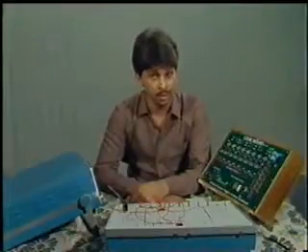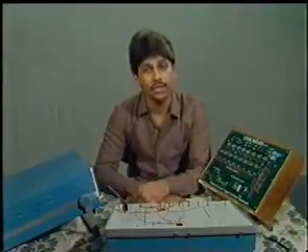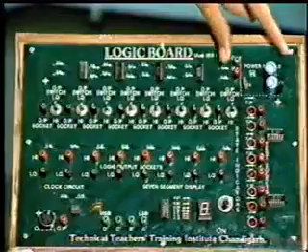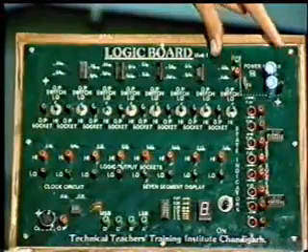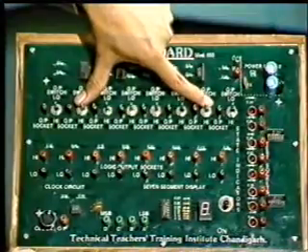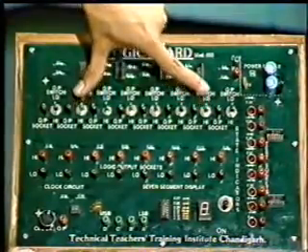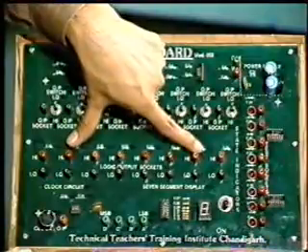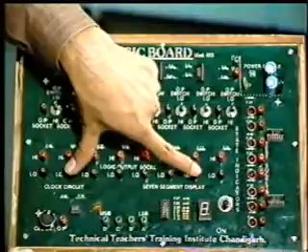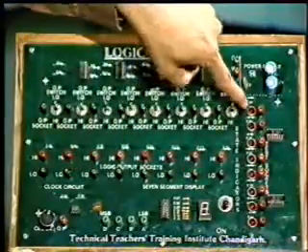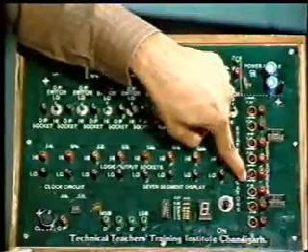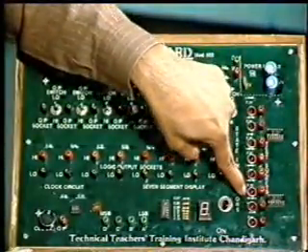To sum up, the testing of a digital circuit requires regulated power supply, variable logic inputs supplied by these sockets and toggle switches, fixed logic inputs supplied by these high and low sockets, state indicators to test the logic level of the test circuit output.